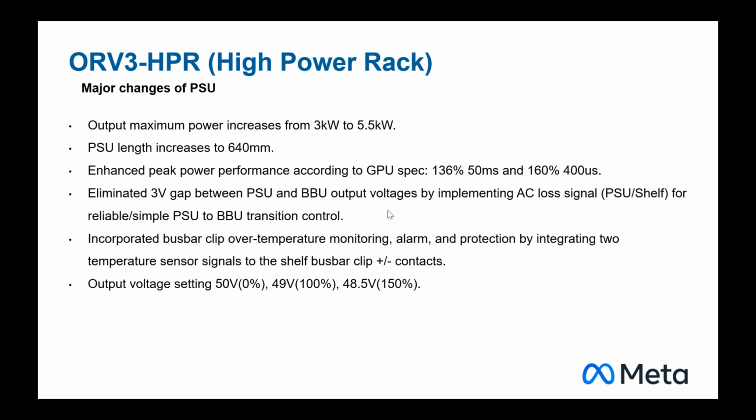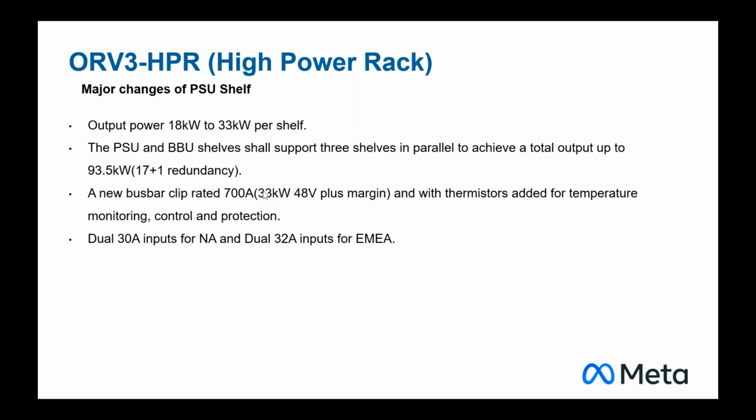The power shelf connector is up to 700 amps. It's quite large current. The IT gear connector has a smaller current, 150 amps, if I remember correctly. So far we don't have it, but they can use the same method. It's quite simple, not very hard. All the major connector vendors already have the solution, and we have the samples. We unified the thermistor as a 10K NTC thermistor.